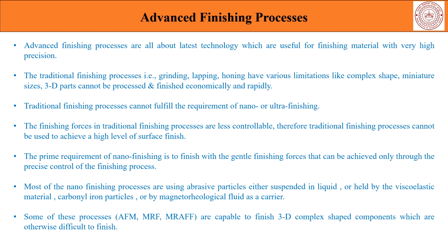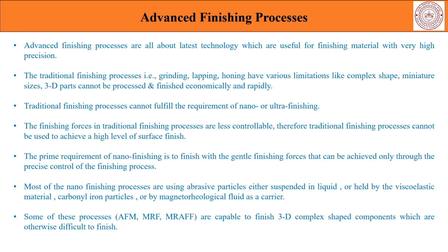And most of the nano finishing processes use abrasive particles, either suspended or held in various viscous fluids or medium, with fluid particles that change the apparent viscosity of the medium because of the line up with external actuation forces like magnetic fields, etc. There are carbonyl iron particles which are mostly used for that purpose, and magnetorheological fluids have a change of viscosity as a function of external actuation. All these properties together can determine the reach of the finish and also the specificity of the finish on surfaces which are ultra small in general.